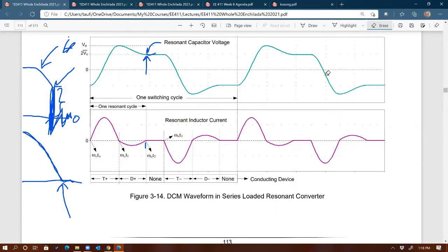Remember earlier I said that this resonant converter is being used for high voltage. And Schottky voltage rating wise, I think Cody asked earlier about the voltage rating of the Schottky's. Schottky diode voltage rating is not high, relatively low, around 250 volts max. PN junction diodes, on the other hand, can go up very high, up to tens of kilovolts.